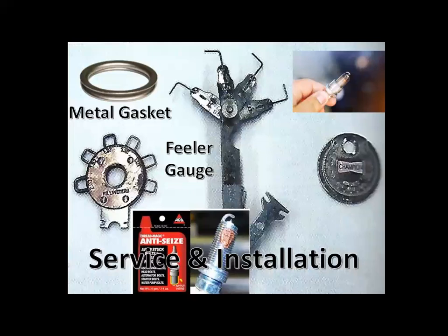Always start the spark plug into the cylinder head threads by hand to avoid damaging these threads. Turn the spark plug into the cylinder head threads by hand until the gasket or tapered seat contacts the cylinder head.